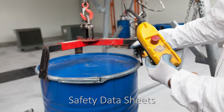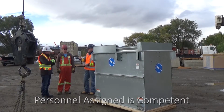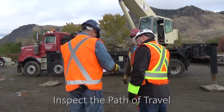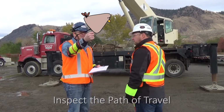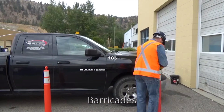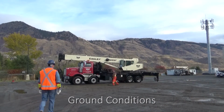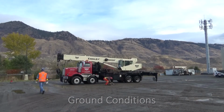If the load or the lift operation may expose workers to hazardous materials, safety data sheets may need to be reviewed. You need to ensure the personnel assigned is competent in the tasks they will be performing. The planning stage will also need to include inspecting the path of travel for the load and crane, and whether there is a danger of the rigging equipment or the load getting caught up in or striking structures, equipment, or workers in the vicinity. You may need to plan for barricades to prevent vehicular or pedestrian traffic from entering the lift area. The crane's path of travel must be assessed to ensure the ground conditions and proximity to other cranes and structures will not create a hazard during the lift.